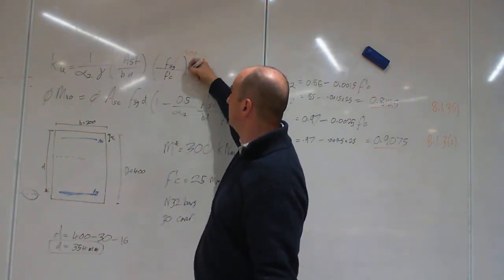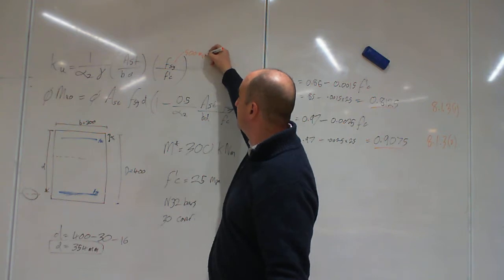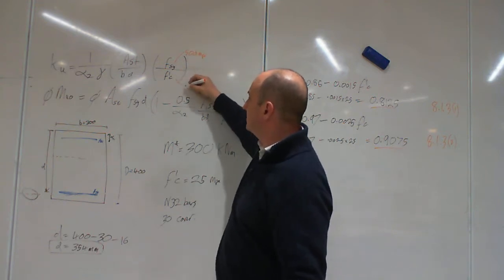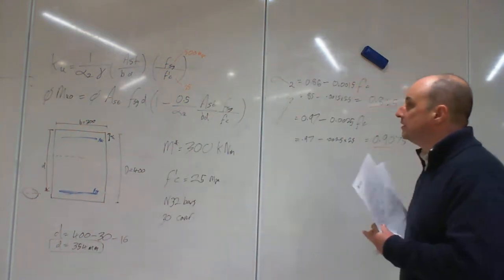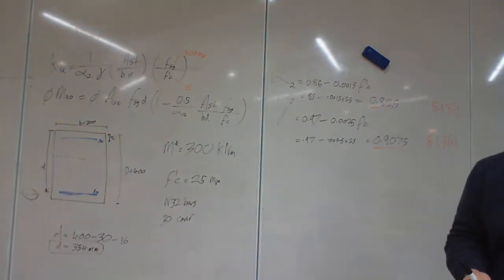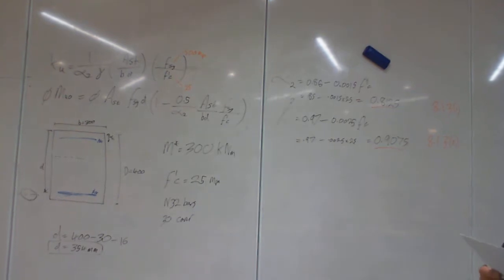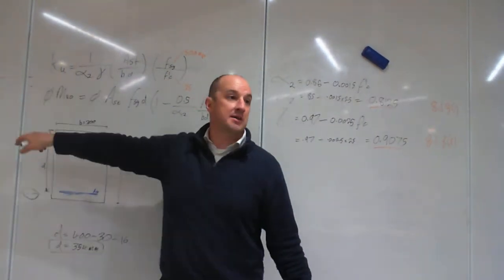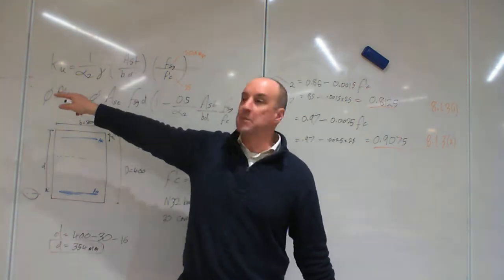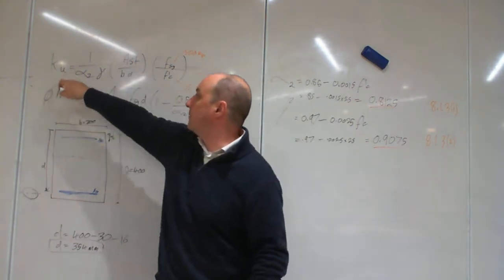500 megapascals. And the strength of the concrete? 25 MPa. All right. So that means that when our Ku is a maximum, that's going to give our highest possible bending moment here. So our maximum Ku.